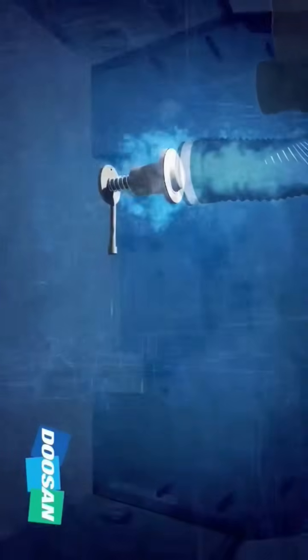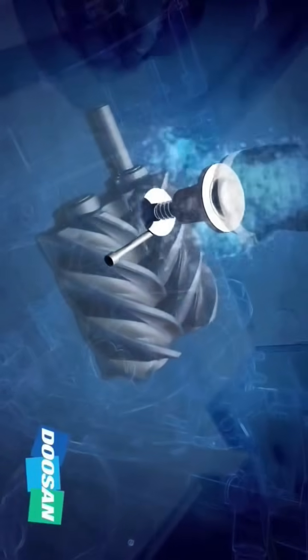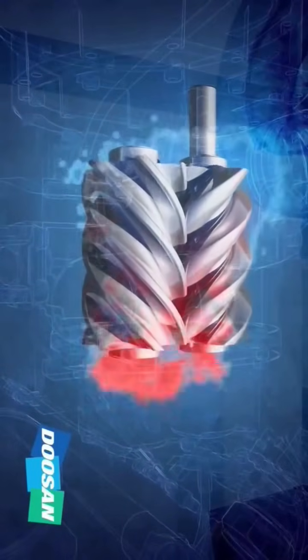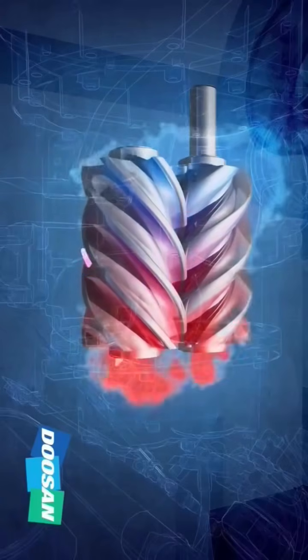Next, air enters the air end, which is a fixed displacement pump that uses two helical rotors to compress air. As the rotor screws turn, they form a partial vacuum which sucks air into the helical rotors. The amount of air that fills the air end is measured in cubic feet or meters per minute.